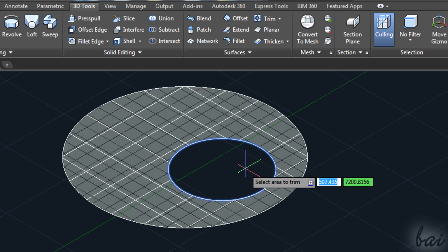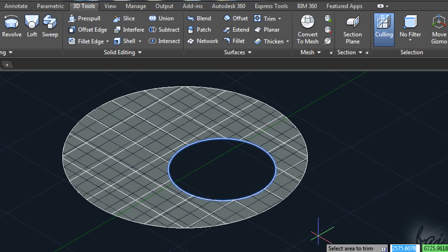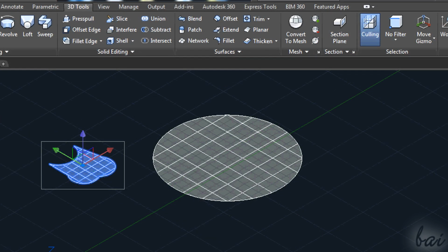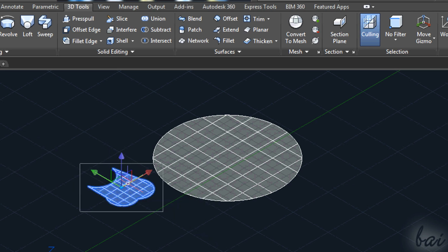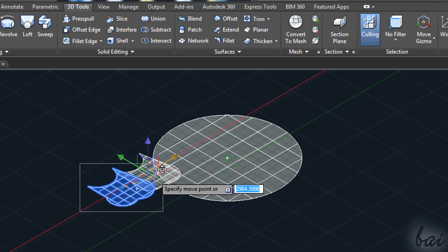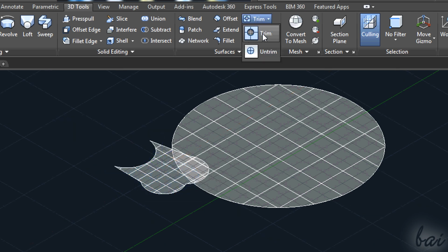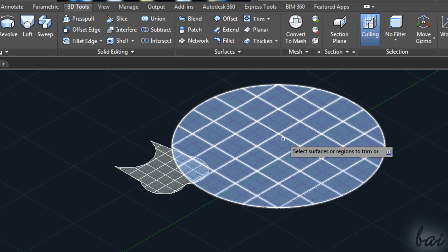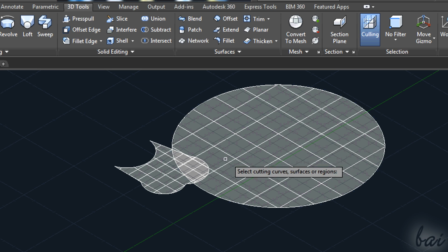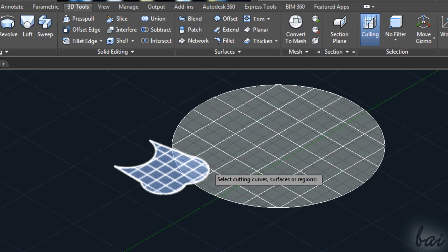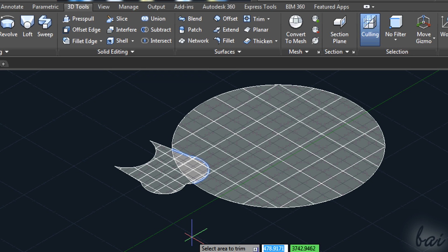You just have to choose which is the part you want to remove. Mind that any surface must have its contour included through groups, as seen before. If you don't do this, the command won't work properly. So do keep surface and contour together in groups.